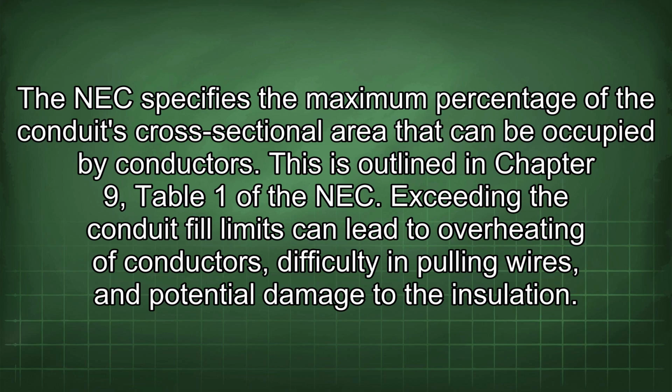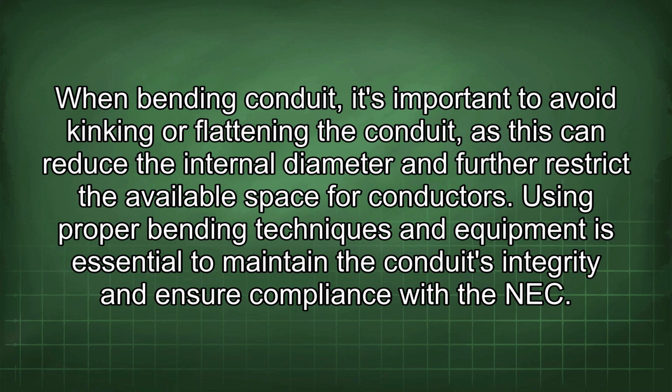Exceeding the conduit fill limits can lead to overheating of conductors, difficulty in pulling wires, and potential damage to the insulation. When bending conduit, it's important to avoid kinking or flattening the conduit, as this can reduce the internal diameter and further restrict the available space for conductors. Using proper bending techniques and equipment is essential to maintain the conduit's integrity and ensure compliance with the NEC.